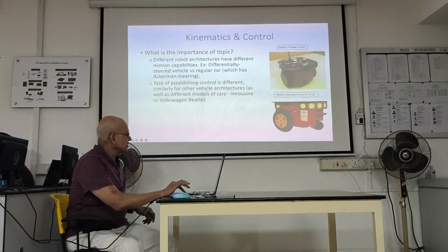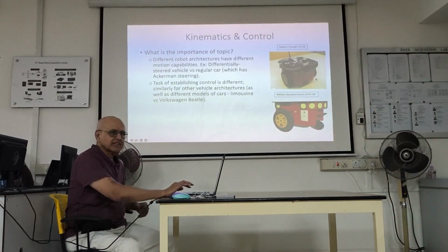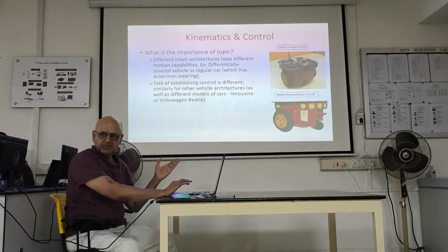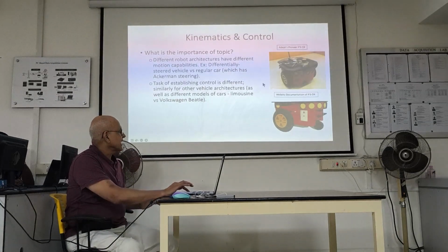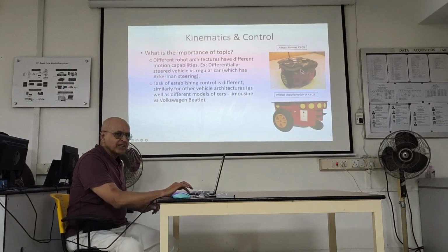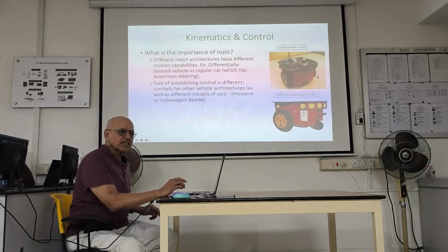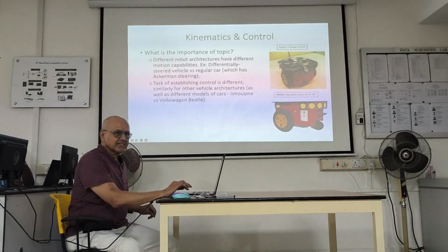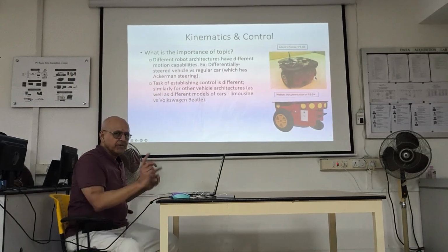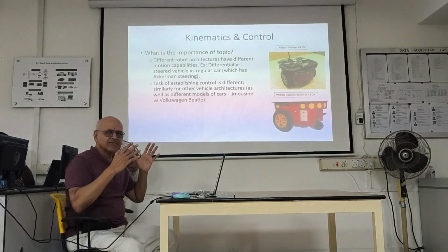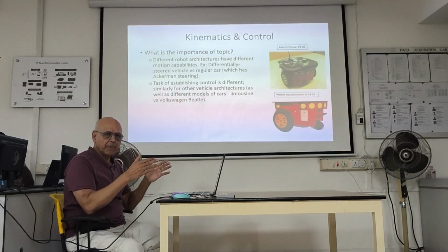So essentially, if you want to go straight, both of these wheels need to be driven at the same velocity. In the case of the TurtleBot, we used 0.4 meters per second, remember? That's the forward velocity of the robot, but that's not the velocity of the wheels. The velocity of the wheels, you'll see tomorrow, contribute to the velocity of the chassis. The velocity of the wheels can be different. If they are the same, the robot will move on a straight line.